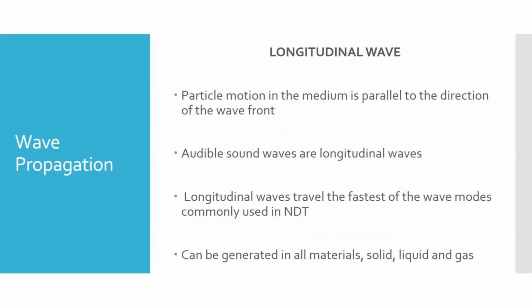And that's what the audible sound waves are that we're using. That's primarily what we're getting. The very edges of the wave exhibit the transverse or shear wave effect. But for the most part, what's coming out of my mouth, what's hitting your eardrum, what we're going to be putting into the part when we do ultrasonic testing, that's going to be a longitudinal wavefront.